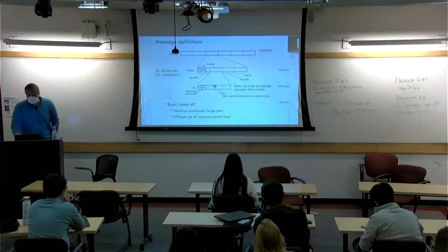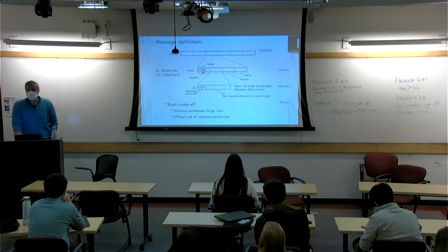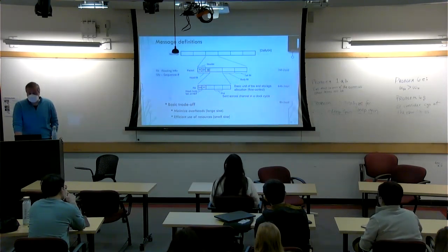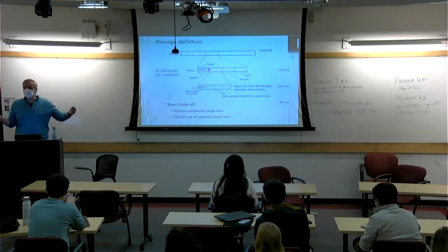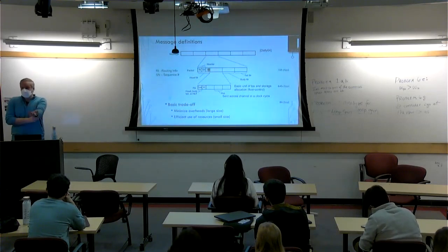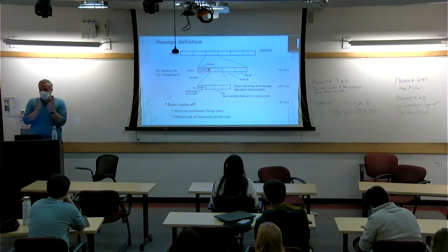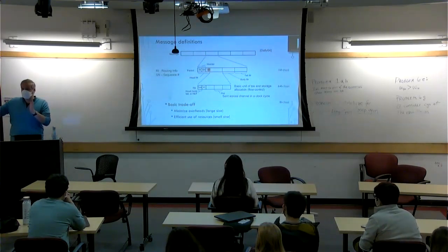But in this case, it's not actually that much if you look at it. Let's say a packet was a cache line, right? So 1 kilobit, the header would be like 64 bits. That's why you chunk it into flits. A flit could be even smaller, 32 bits. And you try to minimize this routing information. I don't want to have a 16-bit or 32-bit string telling where I'm going. I want to have some simpler tag, as we'll see, or use dimension order routing to really simplify that overhead, right? But you're right, it is definitely always a balance of the header information, the bookkeeping in the network, versus all the payload that you're sending.